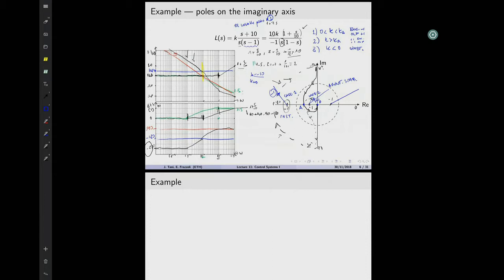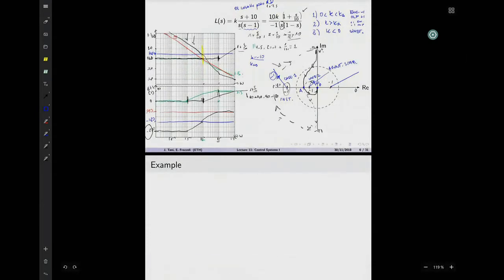So if we apply the Routh criterion to the denominator of the closed loop transfer function, we should be able to find the value of K such that the system transitions from stability to instability, which is exactly the Ka we need. So how do we do this?